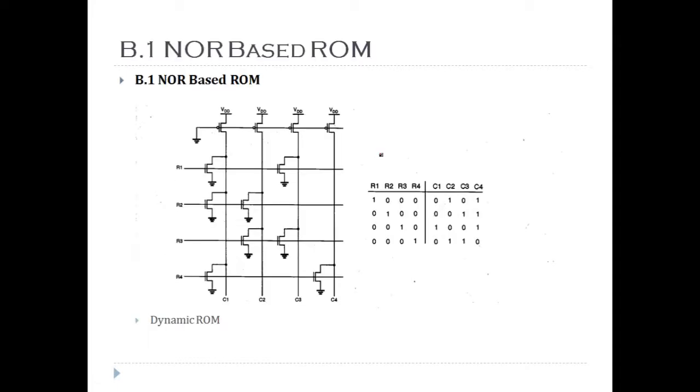Now, even though the circuits are shown like here, the density is the major issue. Can we work on the density of this? So one thing can be done. Now here, if you look at row 2 and row 3, you can see its drain is connected to the bit line or a column line, and sources are connected to ground. Here also at this point, you can particularly say in R3, drain is connected to bit line or column line, and source is connected to ground.